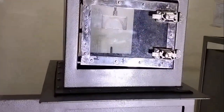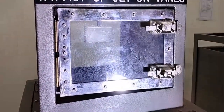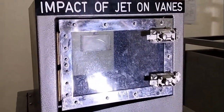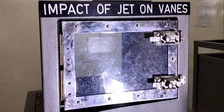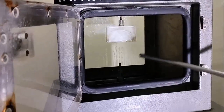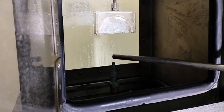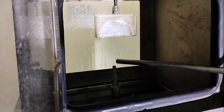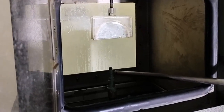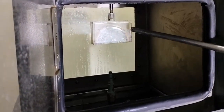Now we are going to discuss the impact of jet on vanes. First, I am going to tell you about the main parts of this experiment. The main part is the nozzle. In our lab, we have three different nozzles: 4 mm, 5 mm and 6 mm. For our experiment, we are going to use the 5 mm diameter nozzle, and this is the vane.